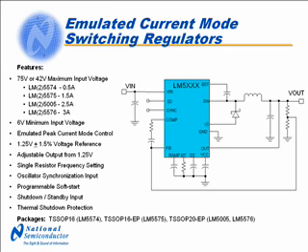Shown on this slide is a buck regulator application using one of our new integrated switching regulators. The new family of regulators employs the emulated current mode control technology. There are a total of 8 devices available with either a 42 volt or 75 volt maximum input voltage, and the current maximum levels are 0.5, 1.5, 2.5, and 3 amps.